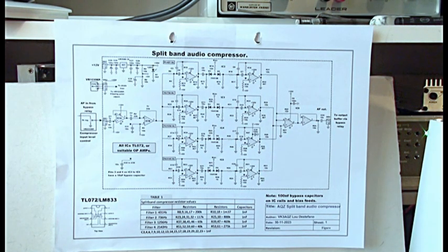If you were to pass speech through these diode clippers without any bandpass filtering, you would be generating harmonics. Every time you distort the sine wave, harmonics will be generated, the level depending on the amount of distortion. The harmonics from a 1 kHz sine wave will be at 2 kHz, 3, 4 and so on. However, if you pass that 1 kHz sine wave through a filter centered on 1 kHz, but not wide enough to go to 2 kHz, you will have filtered out the second, third and fourth harmonics. So the output of the second filter will be back to basically a sine wave.